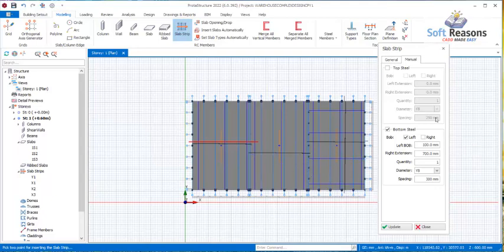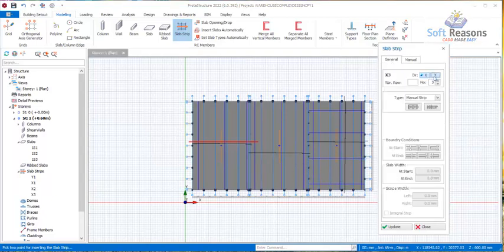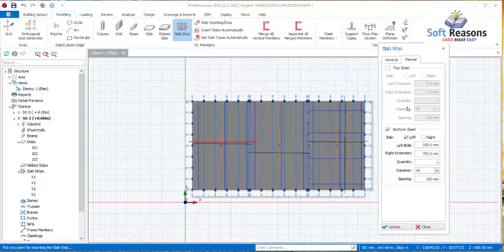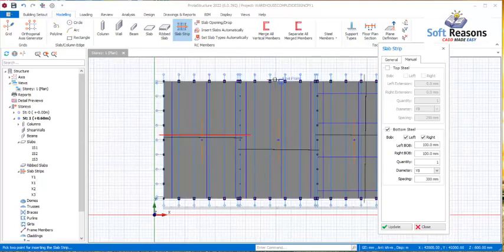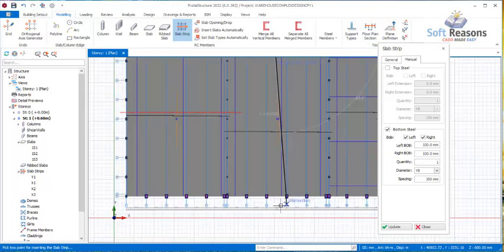After which you have to come over here, change the direction to the Y direction, get back to manual, and then check that we have discontinuity in the vertical direction. So we select these provisions and change here to 100, after which you pick this point up right there, come all the way down, hold the control key, have a straight line and click.